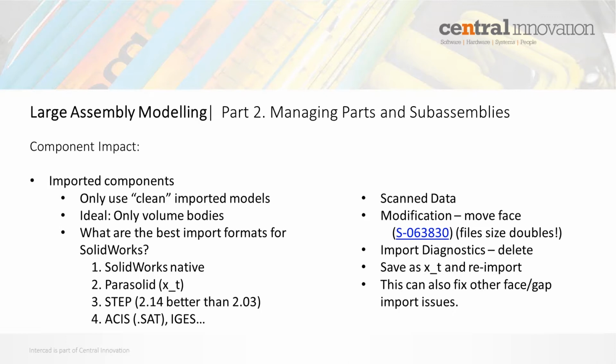The other thing about Scan to 3D is that it's 32-bit architecture. It's really only cut out for importing simple bodies, not whole machinery. I have seen people try and do this. It's not really the ideal mode to bring that sort of data in. And if you get people providing files which are really huge scan data files, you probably want to push back a bit and ask for only the data that they really require you to work with. It's about being efficient when working with large assemblies.